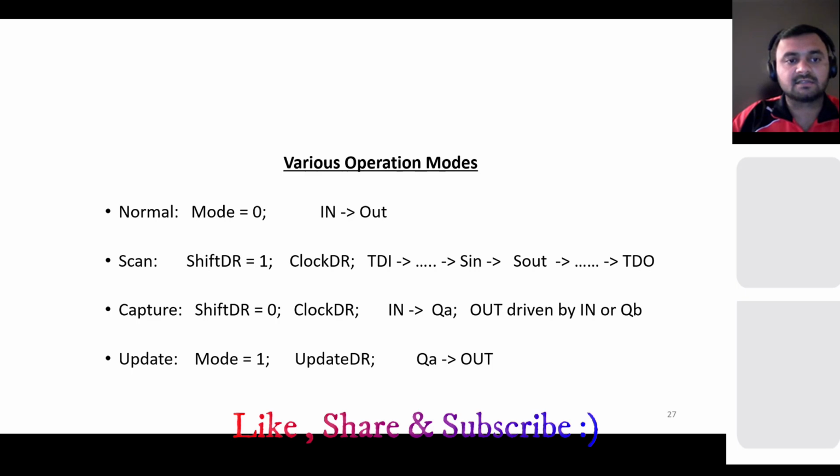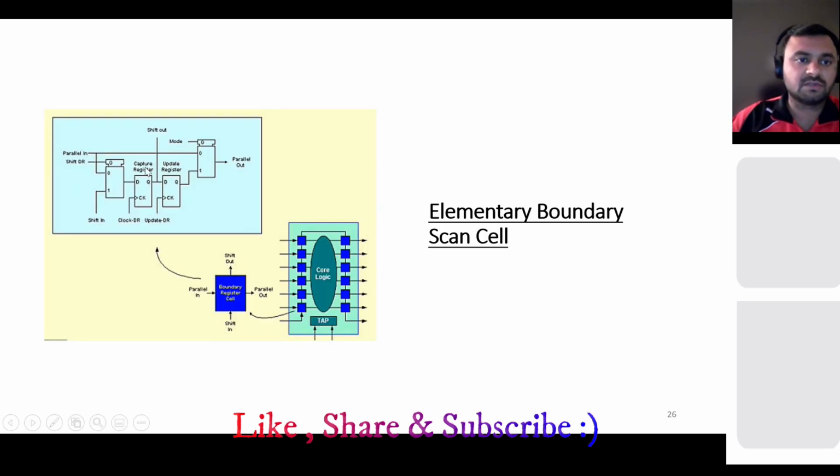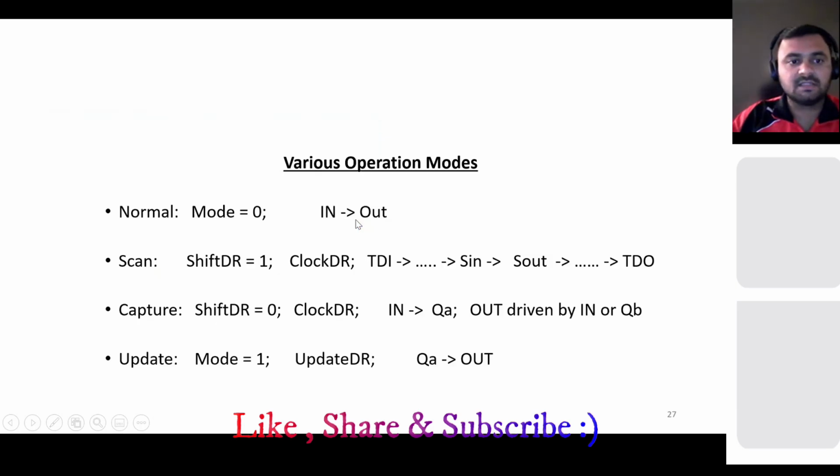Then you want to do the scan. So in scan mode, you put shift DR equal to 1. So basically you use the first mux. So put shift DR equal to 1, and it will select the shifting. Shifting means that from TDI, the data you are shifting. So you will shift it from here, and then based on the clock DR, it will latch it here in the shift out. So that's how it works in the scan part. And in capture, it's the same.